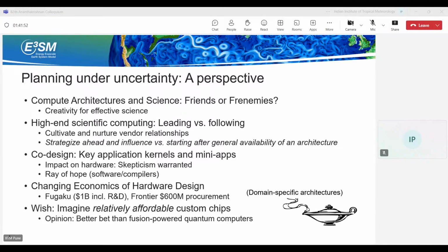You need to communicate key kernels and workload characteristics to them. Even small design trade-offs, like AMD GPUs picked a different cache size from the NVIDIA GPUs, and that hurt a lot of applications. By the time they bake in the chip, it's too late. Sometimes if you give them a part of a benchmark that they can integrate into their workflow, they already know the trace of your application. They will know, oh, a lot of applications will probably be hit by this small change, which we think might be good for AI. Now it's going to kill our HPC. So it's still a useful exercise. You may not be able to influence NVIDIA's next chip, but you are going to influence the next small design decision within NVIDIA's new chip.